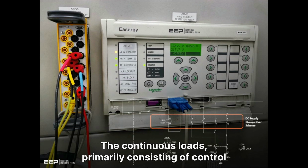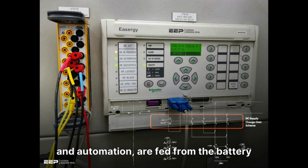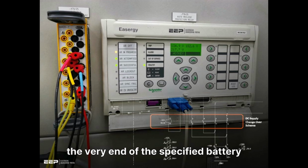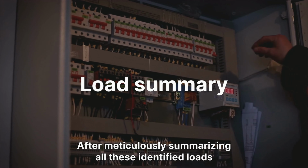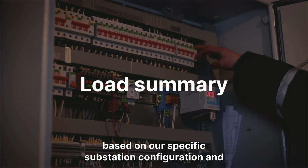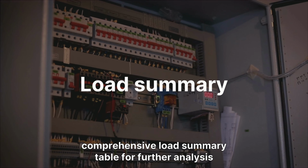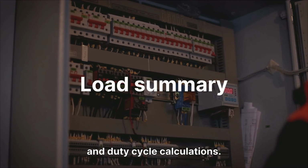The continuous loads, primarily consisting of control and protection relays essential for system monitoring and automation, are fed from the battery right from the beginning and continue until the very end of the specified battery discharge time, ensuring uninterrupted operation. After meticulously summarizing all these identified loads based on our specific substation configuration and engineering proposal, we proceed to compile a comprehensive load summary table for further analysis and duty cycle calculations.